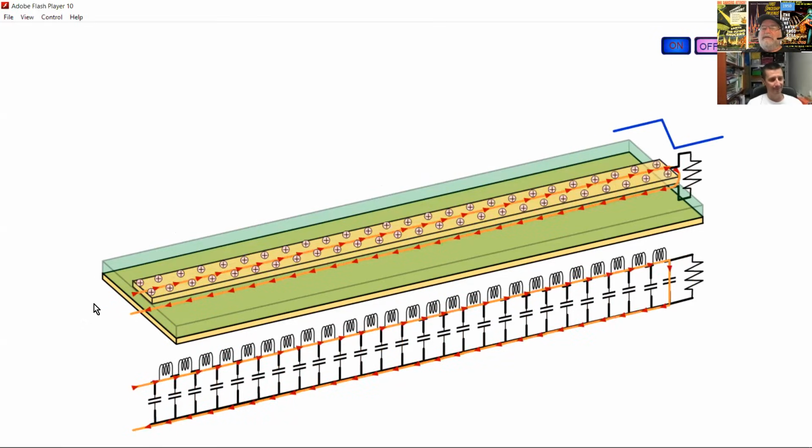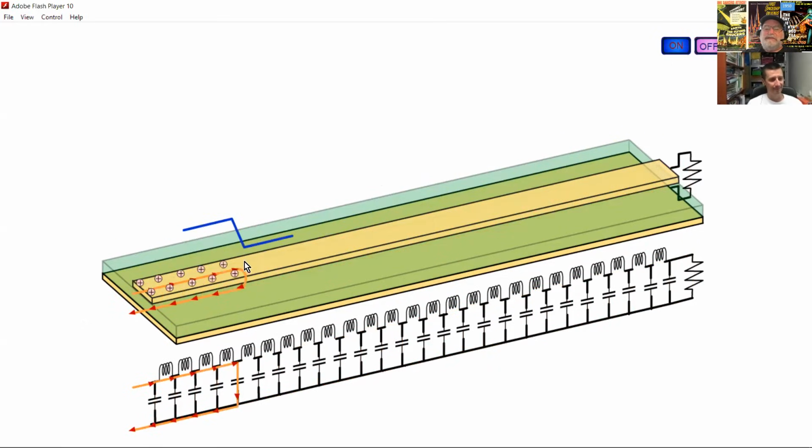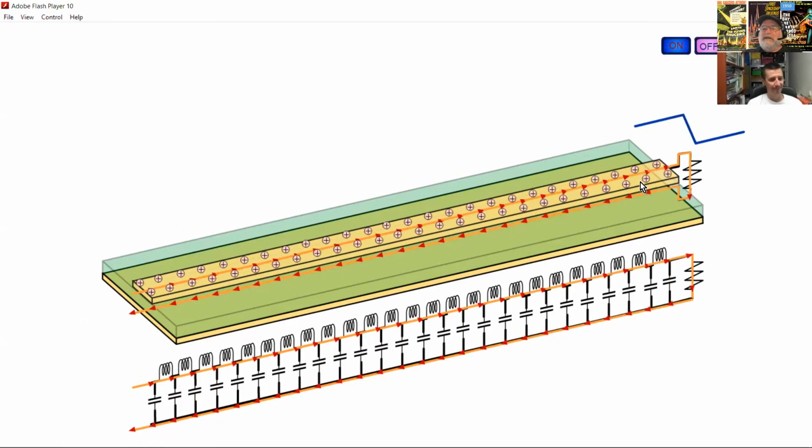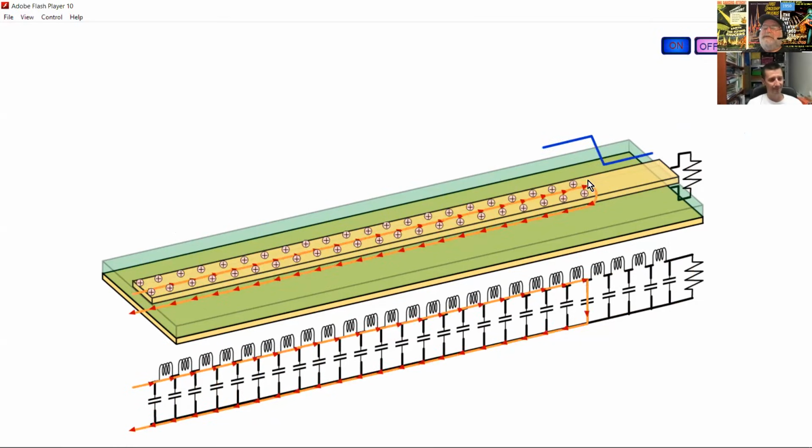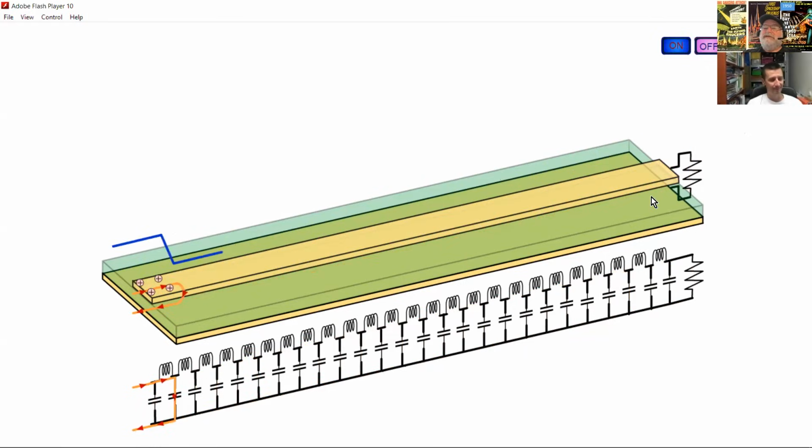And when we talk about the impedance that signal sees as it's propagating down, it is literally the ratio of that voltage that is the signal divided by the current that is the displacement current. And as we move the bottom conductor around, change the spacing, change its shape, anything like that, when we change the return conductor, we influence the displacement current. We change the electric fields, we influence the displacement current, and that changes the impedance.